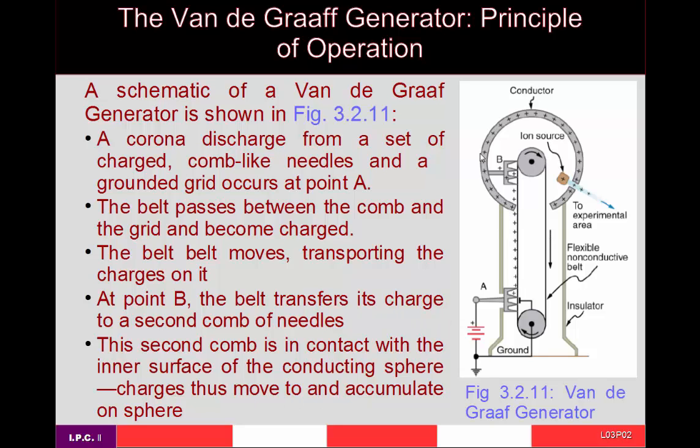So basically, you're able to keep accumulating charges on the surface of this conductor, and by doing so, you are able to charge it indefinitely until you break down the air that's surrounding it. So then you get your ionization breakdown discharge, and that produces a lightning bolt that maybe arcs from the surface of the conductor to the ground. So that's what the limiting factor ends up being.